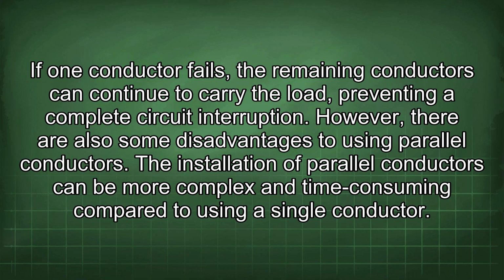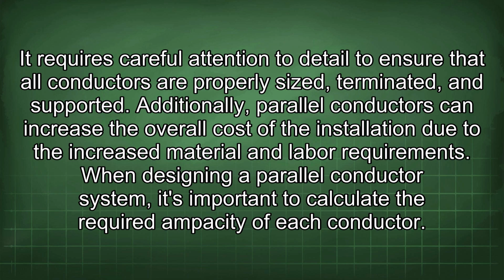However, there are also some disadvantages to using parallel conductors. The installation of parallel conductors can be more complex and time-consuming compared to using a single conductor. It requires careful attention to detail to ensure that all conductors are properly sized, terminated, and supported. Additionally, parallel conductors can increase the overall cost of the installation due to the increased material and labor requirements.